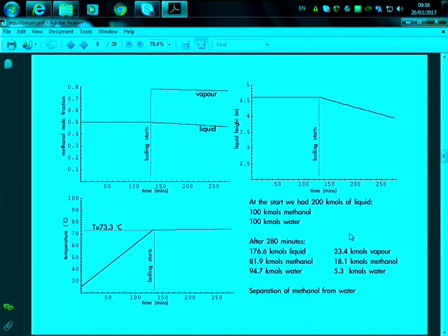So the distillation system in the laboratory was basically distilling, so you had an evaporator, but then you had here a mixture. You didn't have each one of the components going one after the other. So at the end, it became very complicated to characterize the mixture, to characterize what stayed and didn't distill. So that's why distillation columns exist, because you are unable to perform a whole separation process just by doing one distillation like that. Okay.